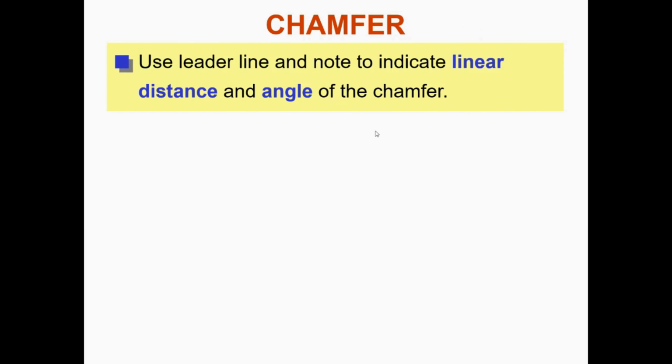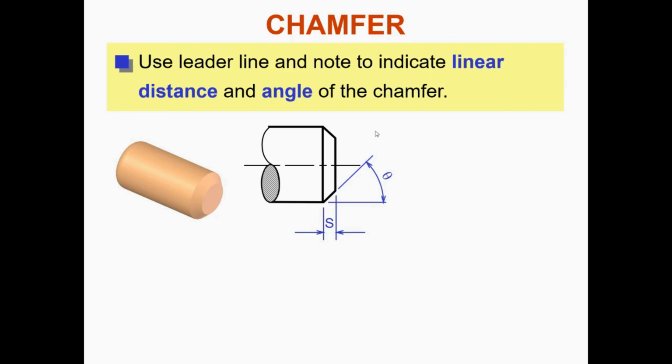Let's move to chamfer. Use a leader line and note to indicate the linear distance and angle of a chamfer. This is an example.